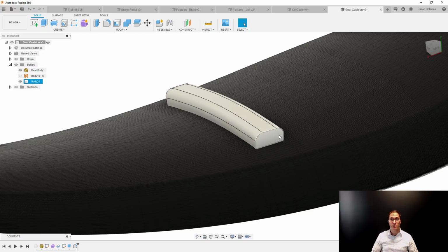I was talking to a customer just the other day, and they actually 3D scan the roofs of vehicles, and they make custom roof racks to fit all the vehicles. This would be an absolute perfect way to make sure that your design, if you're making roof racks, is going to fit that roof. So you 3D scan the roof of a Subaru WRX. Love those cars. And then you could actually go and make a T-spline, make that match that roof, and then use the thicken command to be able to design your roof rails. Right? So this is a great technique for organic surfaces, especially big, kind of smooth ones, and also organic shapes as well.